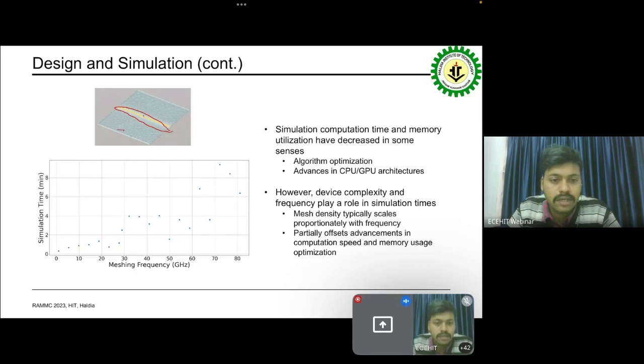And then it's going to become a lot more sparse as you get out to the edge. But what's going to happen is where you have even that relatively high density mesh up near that microstrip, it's going to get even worse as the frequency increases and you maintain everything else the same, which is very often the case. You're not typically going to pull your mesh density down as you're increasing frequency to help compensate for that.